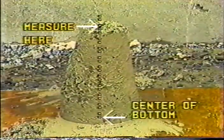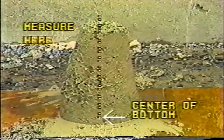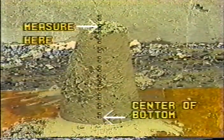Now here's an important point about measuring. Measure from the bottom of the rod to a point on the concrete that is directly above the center of the bottom of the concrete, not at the center of the top. If a fair amount of concrete falls off or shears away, the test is invalid. Make a new test using another portion of the sample.